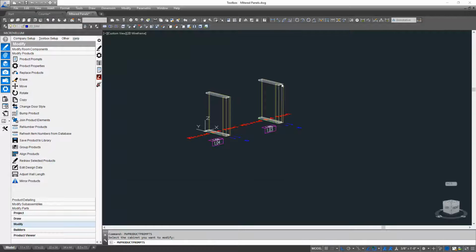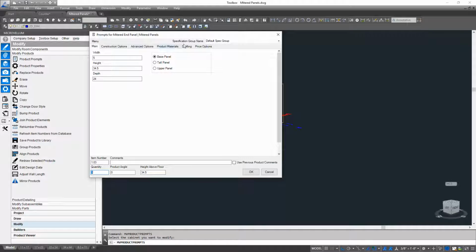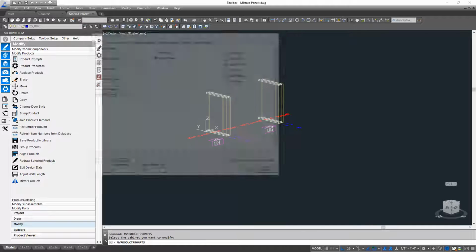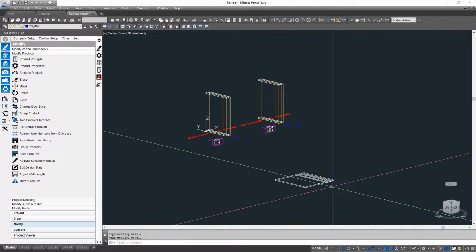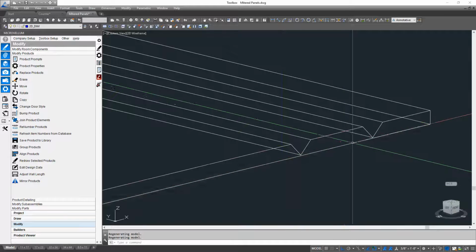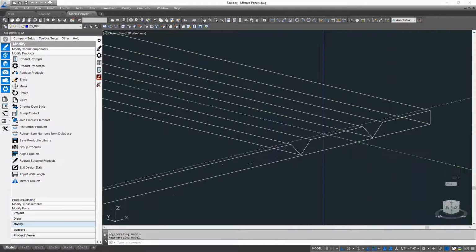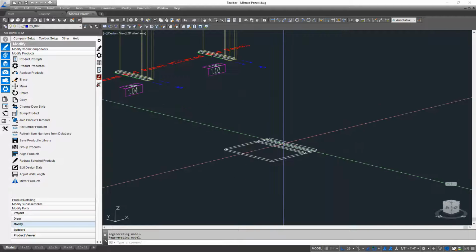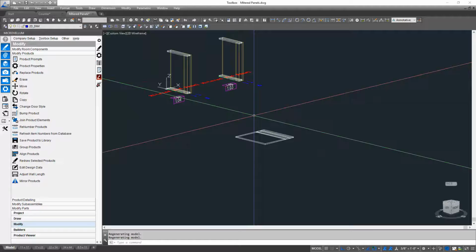And then I have the option on my construction for use miter fold as well. Use miter fold is actually going to make one part that's going to be cut onto the cut list, and there you can see it's making that part with the folds cut in it in order to take that part and fold it up once we manufacture that.